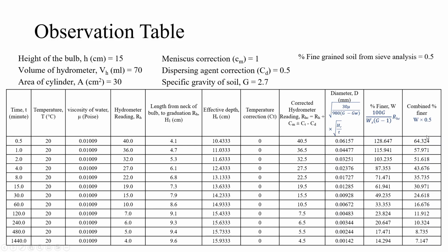Then we will draw the graph of this percentage finer on the y-axis and diameter D on the x-axis in a log scale. So we will find the grain size distribution curve. So I hope you have understood this test.